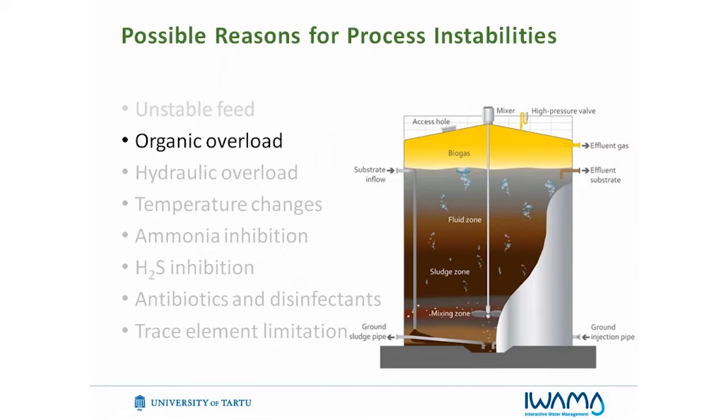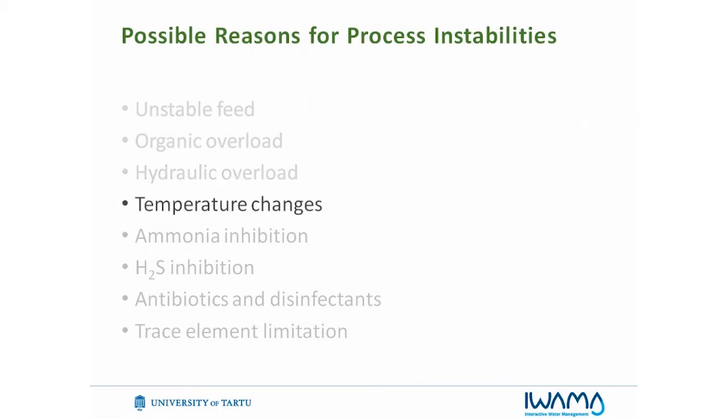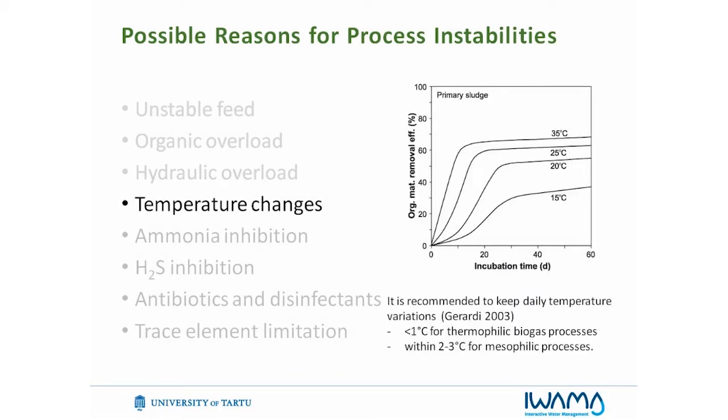And this is probably the first limit, the digestate quality, and the second limit is the drop of the pH in one reactor system, for example. So hydraulic overload also has to be considered, because some of the methanogenic bacteria in the consortia are very slowly growing, and if you hydraulically overload the digester, then you can get a lack of some bacteria.